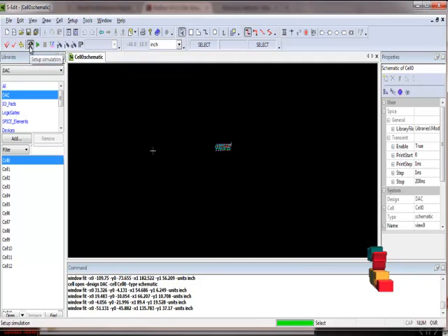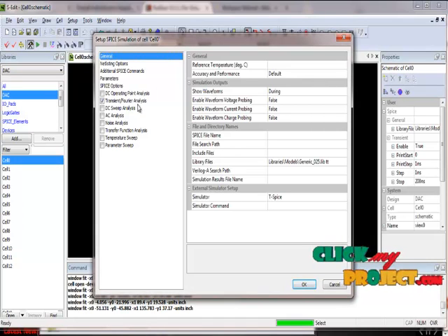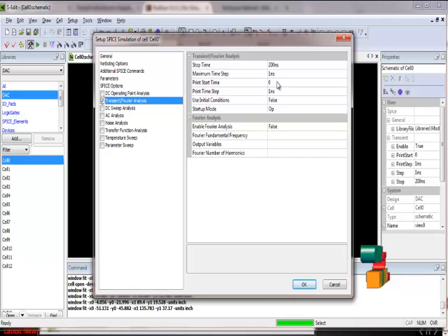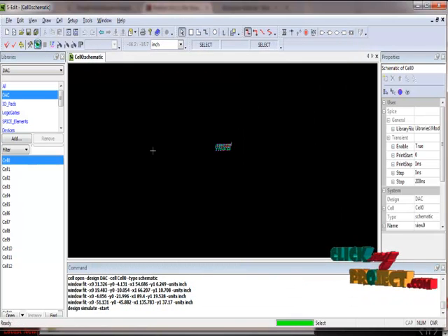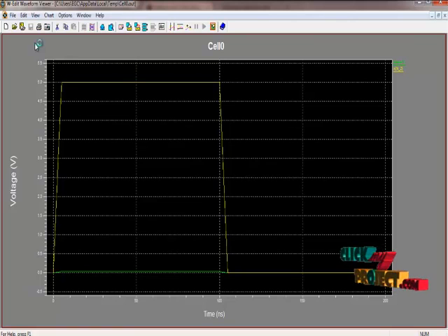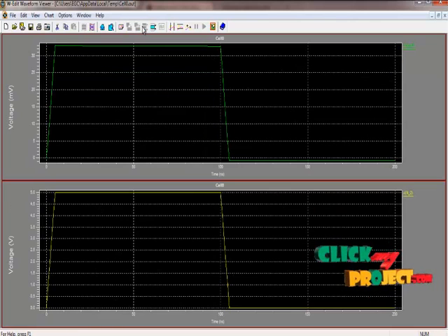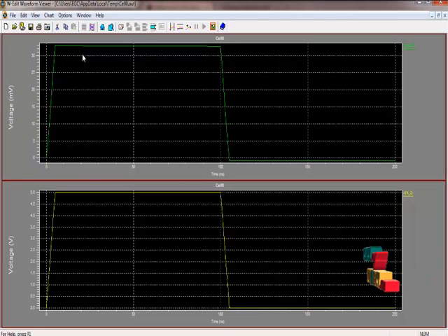Now we implement the first cell and run it. This is the setup simulation process. We use transient Fourier analysis, and we give some instruction sets: stop time 200 nanoseconds and maximum time step 1 nanosecond. These conditions are mandatory. After we finish this, we go to the running process, and automatically the power calculation process and the edit waveform viewer open. Here we show the DAC digital input and voltage output, so this is the input and output voltage of the digital to analog converter.